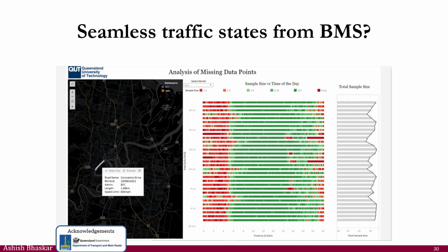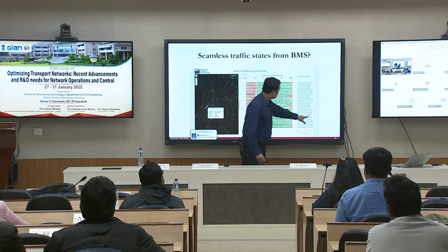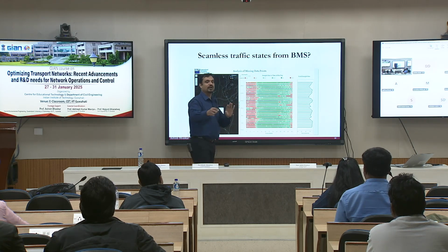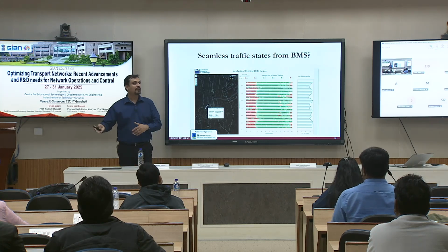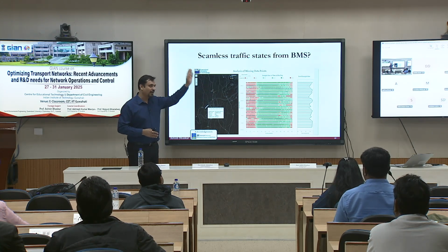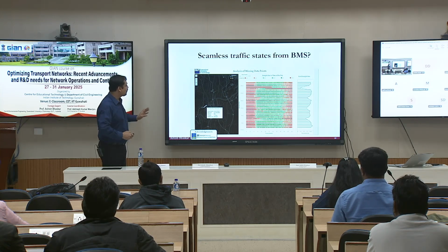Good, yeah. Brisbane is a morning city, yes, 5 a.m., yes. So this is as per your expectation? Yes, because you don't expect too much traffic or too many observations in the midnight, during daytime, and it is green. Very good. Number of total samples for the whole day is around 3,000, and it is varying from one day to another day, which makes sense, as we have seen that weekends might have a lower travel time compared to weekdays, and so you do not have a consistent one. It makes sense, right? Let's go to another road.